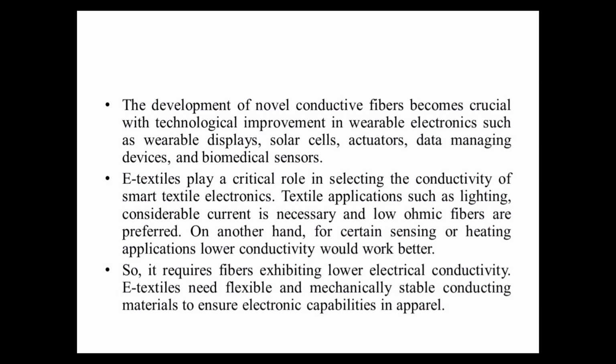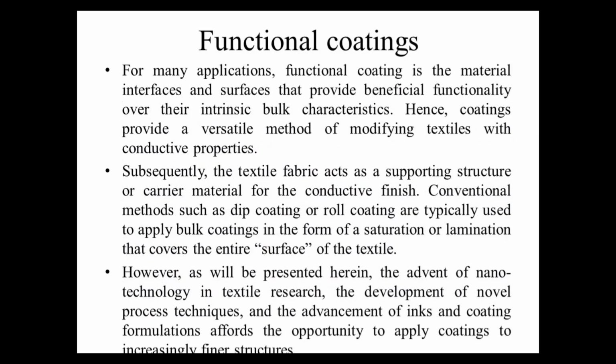For textile applications such as lighting, considerable current is necessary and low ohmic fibers are preferred. On the other hand, for certain sensing or heating applications, lower conductivity would work better, so it requires fibers exhibiting low electrical conductivity. E-textiles need flexible and mechanically stable conducting material to ensure electronic capabilities in apparel.